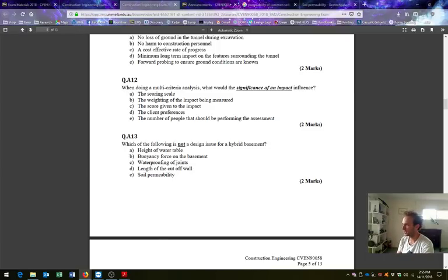2017 A1, 60, yes. Incremental launching, no. So it's too far to incrementally launch. You've got too many spans. Yes, so a barge, yep. Lifting temporary piles takes lots of time. But if you're in real deep water, you can get really big, heavy barges that are capable of huge lifts. You can lift the entire span in one lift and actually do it rather quickly. There's an example up in Canada. I think Jeff talked about it at the end of his lecture.